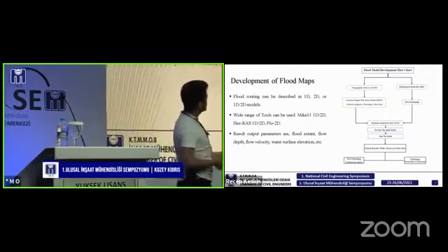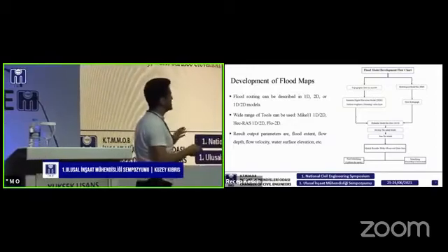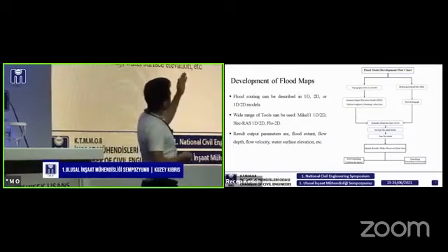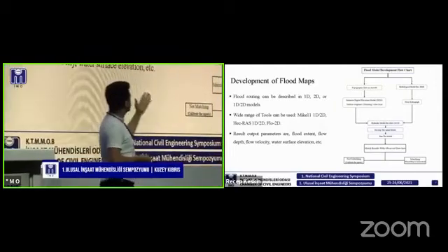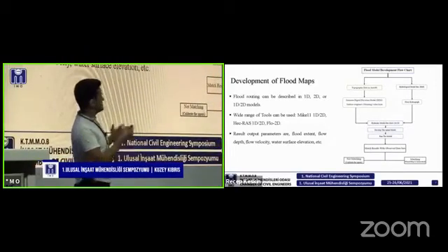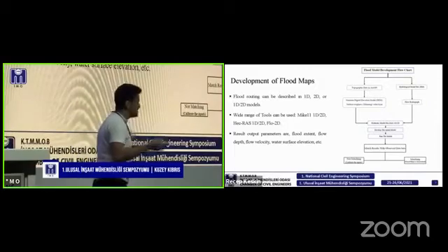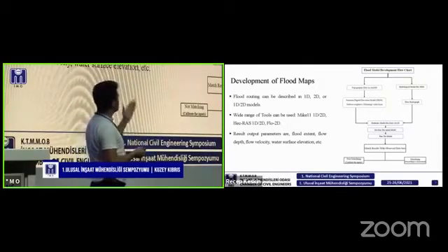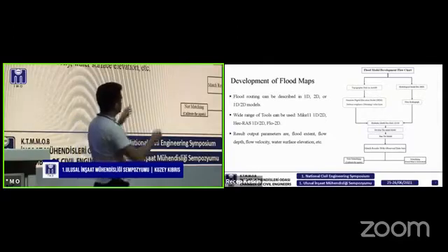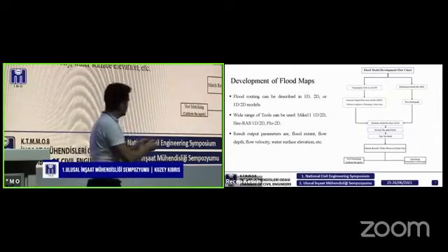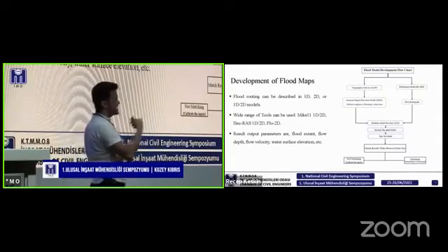This flow chart that I've prepared can show briefly what kind of steps we take. We need to have our topographic data. We develop that using ArcGIS. Then we also need a surface roughness Manning layer, as we call it. And we also need our hydrological model for the flow hydrograph. We put this together in a hydraulic model, and then we develop the initial model.